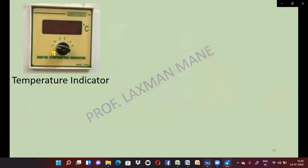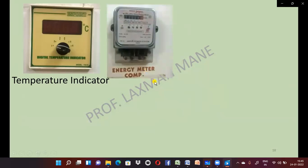Temperature indicator gives readings at four locations in the vapor compression refrigeration system: 1 is the temperature after compression, 2 is the temperature after the condenser, 3 is the temperature after the expansion valve, and 4 is the temperature after the evaporator. Energy meter is used to measure the electrical consumption of the compressor.